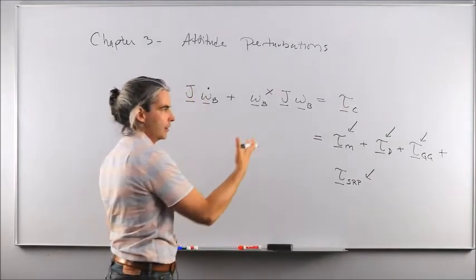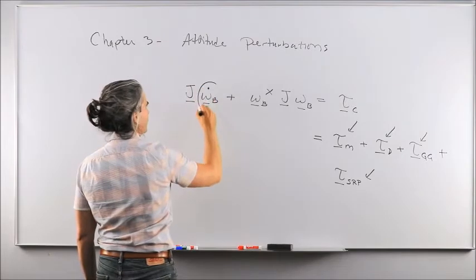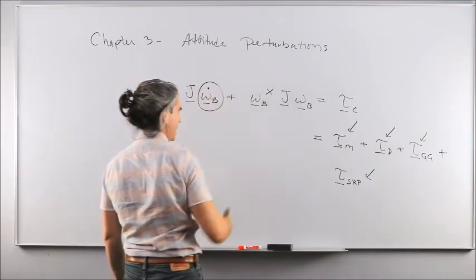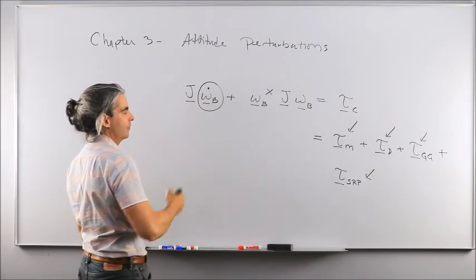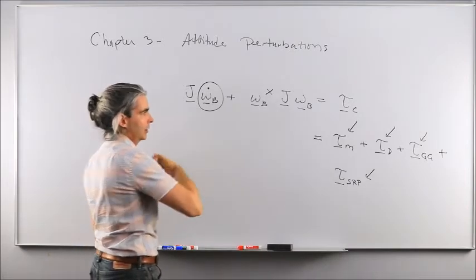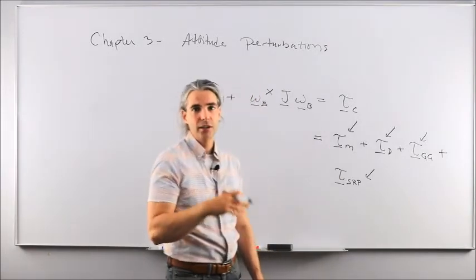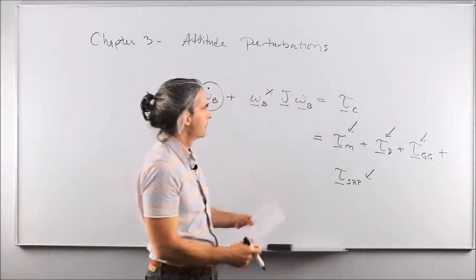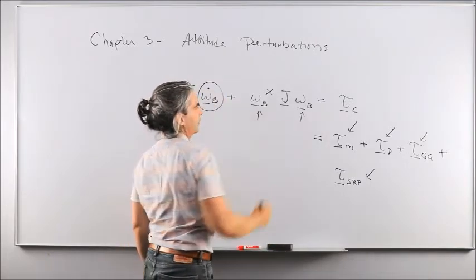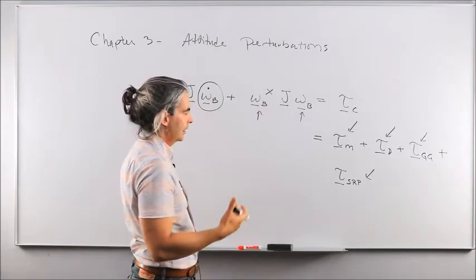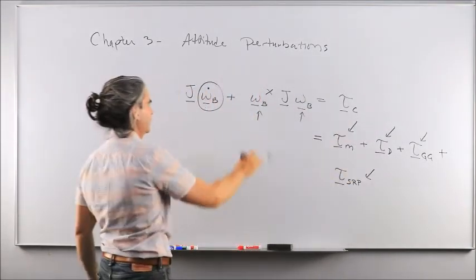And then we could simulate that in MATLAB Simulink to get an expression for omega b dot, integrate that, get omega b, feed omega b back into these equations of motion, repeat the process, and ultimately feed omega b to kinematics, and then see the time evolution of the orientation of our spacecraft due to some initial conditions on omega b and onto the attitude itself under the influence of perturbing torques affecting the overall motion.